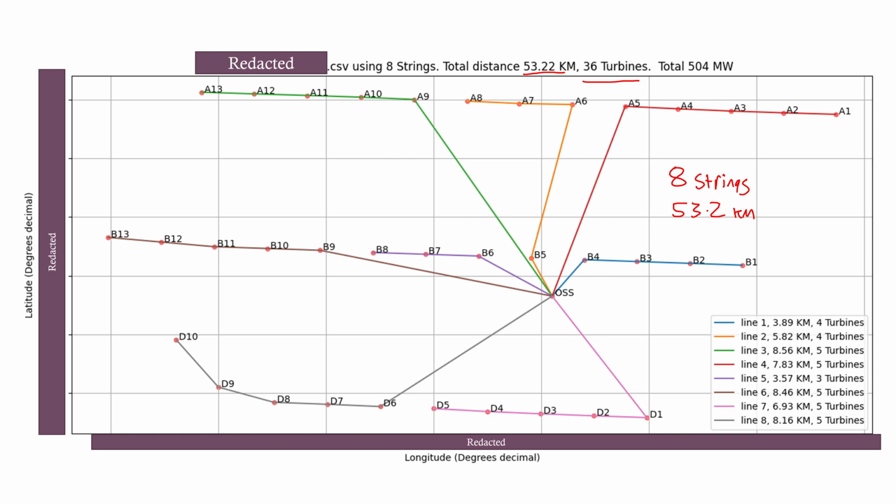So if you can imagine, if you had a much more complex layout where the turbines aren't in such nice straight lines, then you can actually get it wrong. With the code, I've also allowed you to specify the individual water depth at each turbine, because of course that will affect the cable length, and also a snaking allowance, which is how much we need to adjust the cable length to cover, like going around sand waves or boulders or anything else that might be down there.